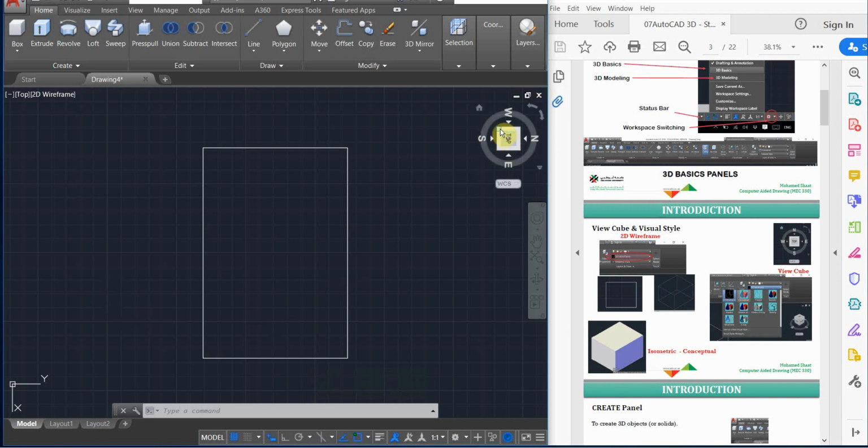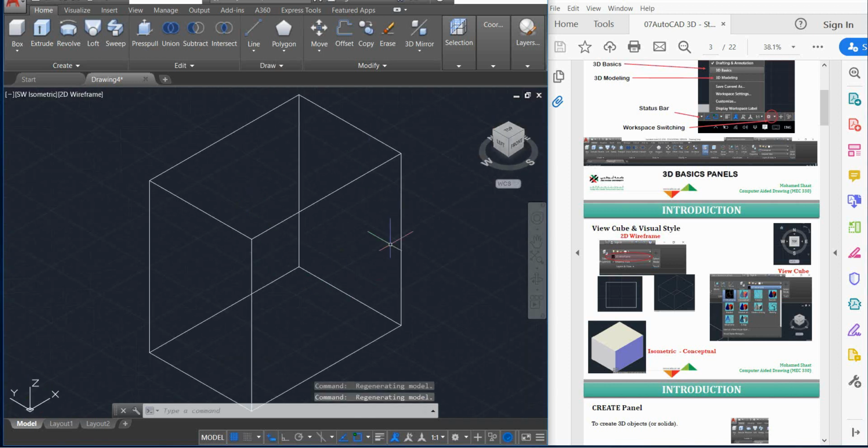To do so, one of the things you can do is click on one of the corners. As you can see, as you move, you can align or give focus. If I click on this corner, I'm asking AutoCAD to rotate or represent the 3D solid at an angle that puts the focus on this corner. And if you remember our definition of the isometric, and the difference between the isometric and the oblique 3D solid, as we discussed in the projection, the isometric gives focus on the corners. So if I click on this one, definitely I'm going to see the object like a three-dimensional solid.